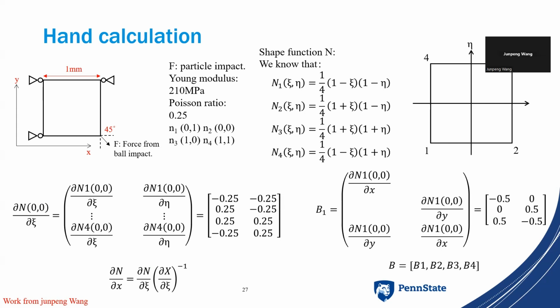and based on some very basic finite element method, we can also acquire the relationship between a small coordinate system and the whole coordinate system, which gives us a relationship for the stiffness matrix. We first need to know the strain relationship between the 2 coordinate systems, which means we need to know the matrix B. This is related to the shape function.